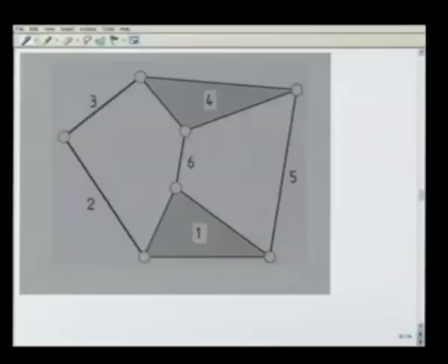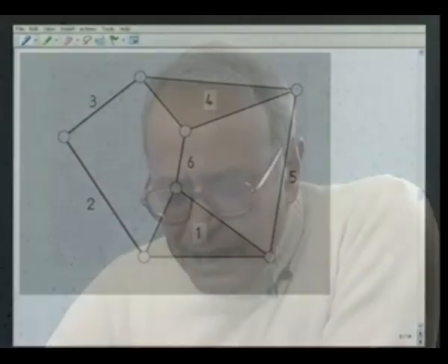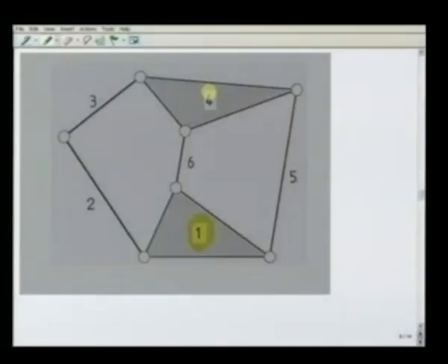As another example of a 6-link mechanism with 7 hinges, we can get the following figure. Here, as we see, there are two ternary links, namely 1 and 4. However, unlike in a Watt's chain, these two ternary links are not directly connected to each other, rather they are connected via this binary link number 6.